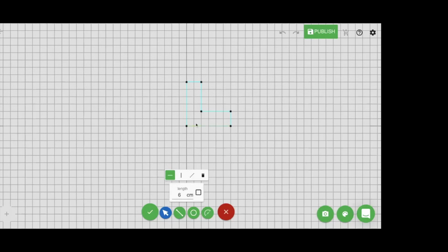The options pop up based on what you click. So if I click 2, holding Control or Command on a Mac, I now have these 2 lines selected, and there's an angle. It's already filled out showing it's 90 degrees, but if I really wanted to make sure it's 90, I can make them perpendicular. I could lock it by pressing 90 degrees, so now it's perfectly 90 all the time. I could type in a different angle between those if I wanted to make it a 45-degree angle.